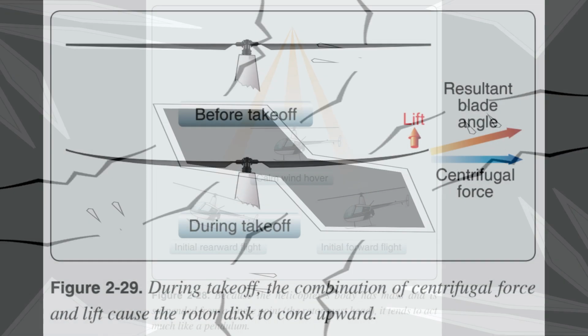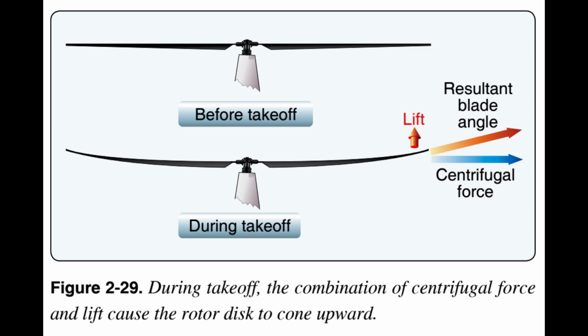Coning. In order for a helicopter to generate lift, the rotor blades must be turning. Rotor disc rotation drives the blades into the air, creating a relative wind component without having to move the airframe through the air as with an airplane or glider. Depending on the motion of the blades and helicopter airframe, many factors cause the relative wind direction to vary.